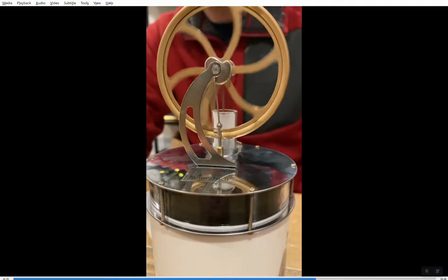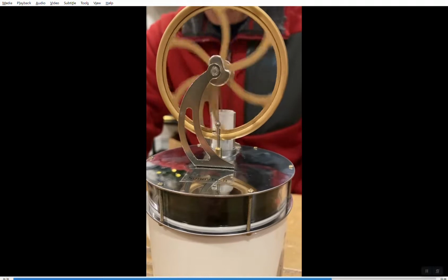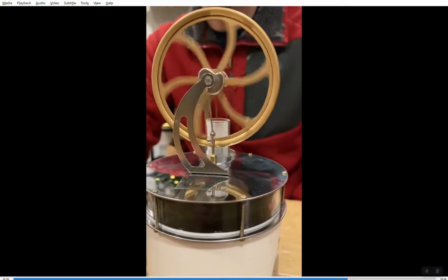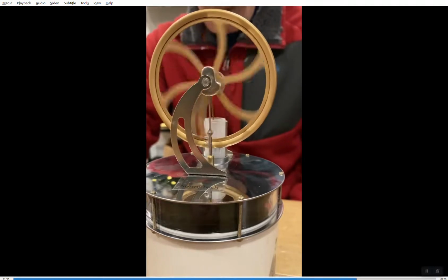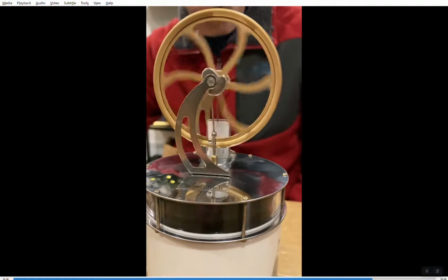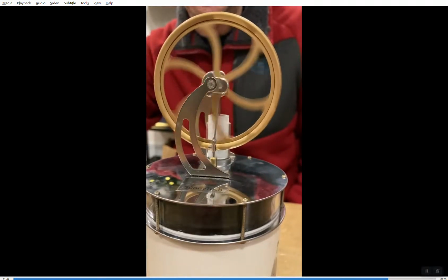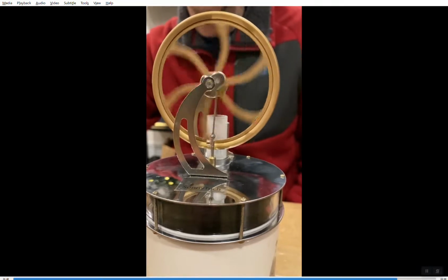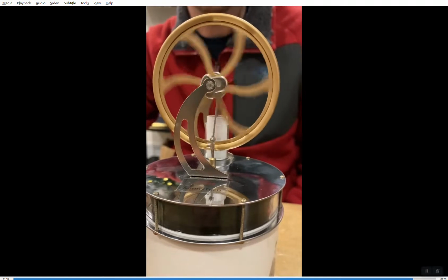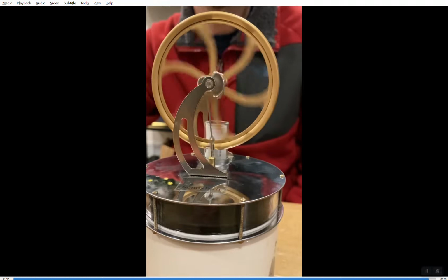This is the type of engine, a Stirling engine, that is not an internal combustion engine like your car. It's actually an external combustion engine because our heat source is outside of the piston. So we have the two pistons, but our hot and cold temperatures are both outside of those. So essentially running what is as close really as we can make to a Carnot cycle. These are kind of nifty little engines that can use external heat sources to be able to create power.